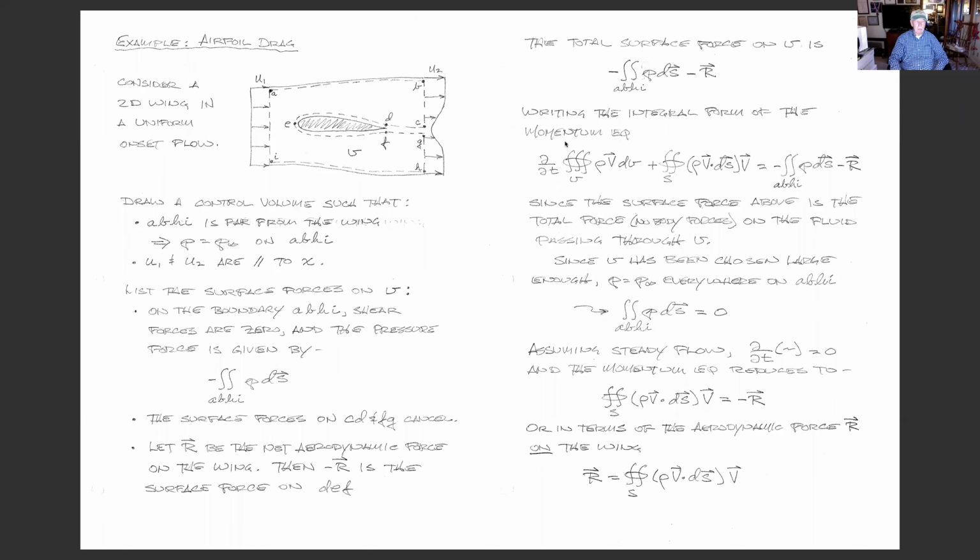And hey, that momentum change to take the downward flow into the engine and straighten it out came out exactly equal, what a surprise, to the free lift. A fundamental error in the control volume. Time and again, I see that.